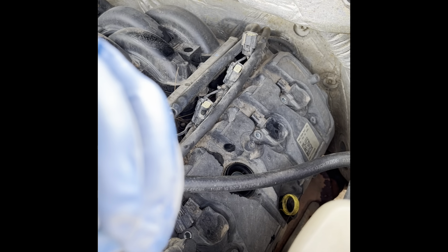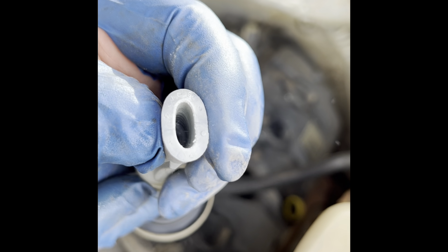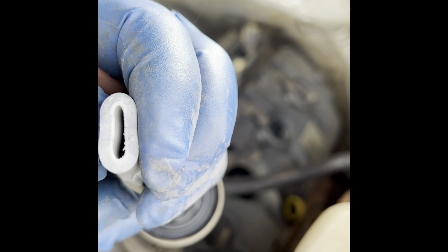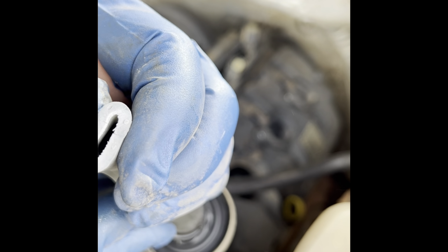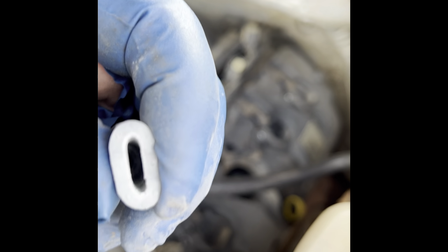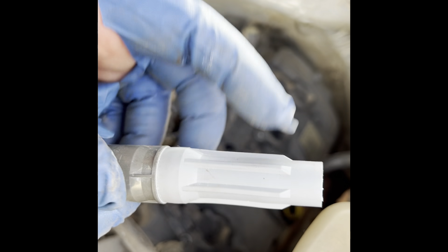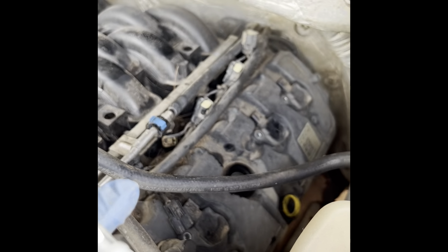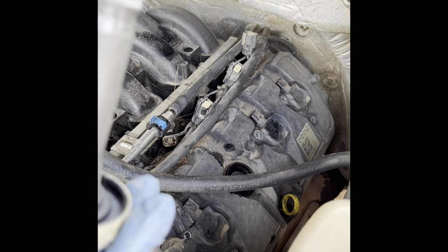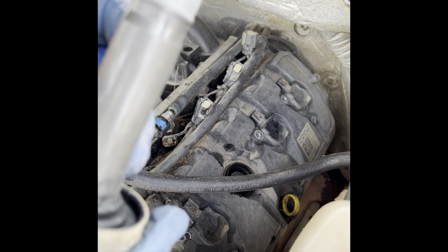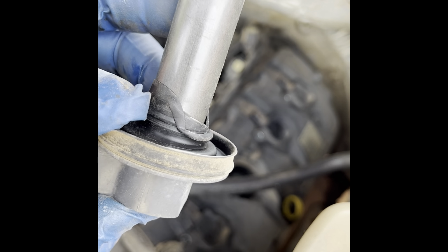You also want to check the boots. Get it in front of the camera, make sure they're not dry rotted, and these look pretty good. They'll get cracks in them across, and then they'll arc through this boot into the side of the head. So see, that gasket's kind of messed up on that one. Whoever was in there last.